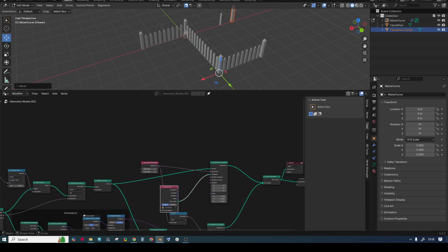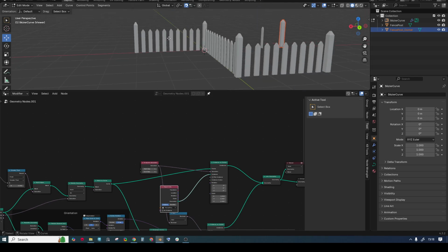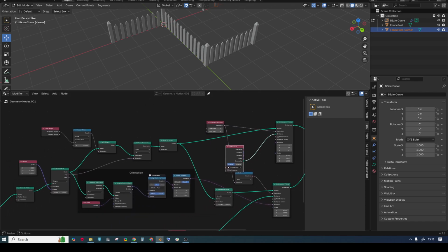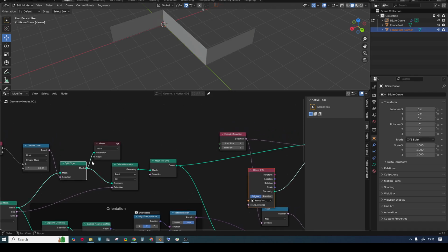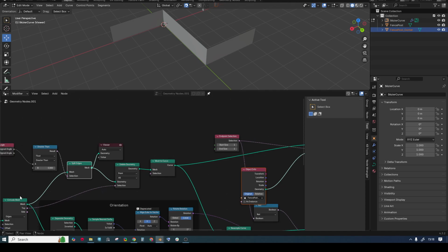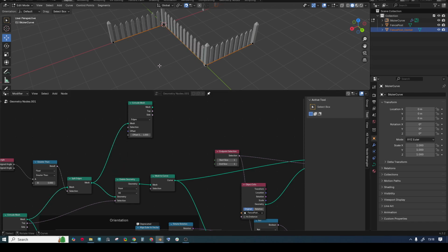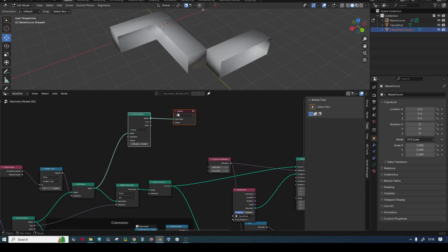So now if we want a transversal element that is gonna connect these in-betweeners, we need to create that from the split edges, because we know we have the split edges, and if we extrude this and transform them, we're gonna have the connected piece of the in-betweeners. So I'm gonna control shift left click, and you can have the preview.